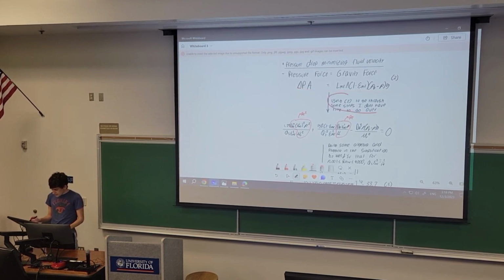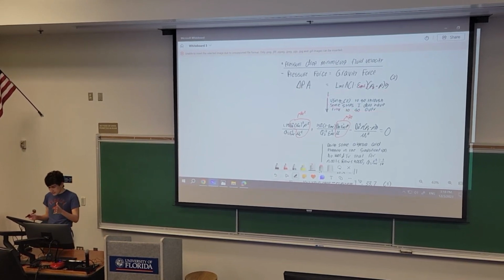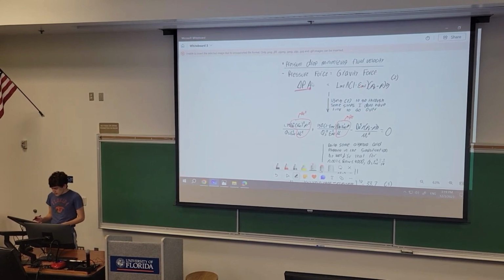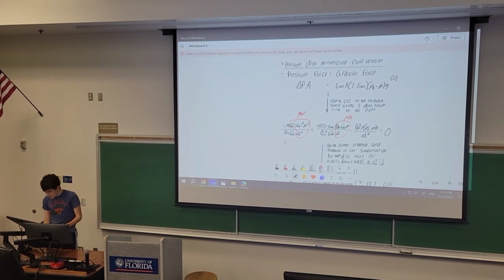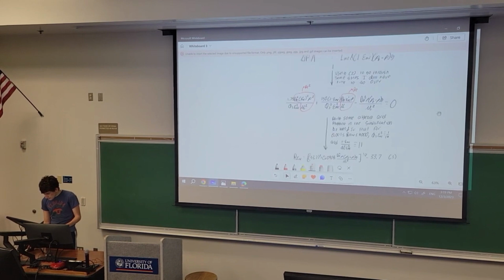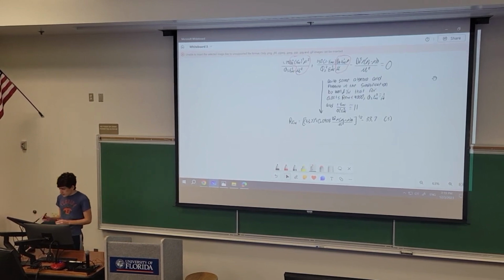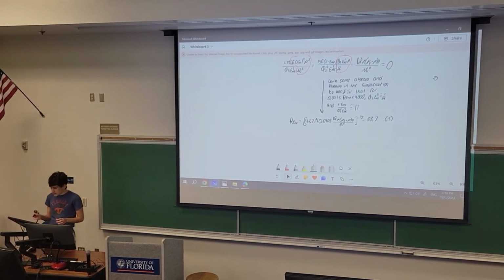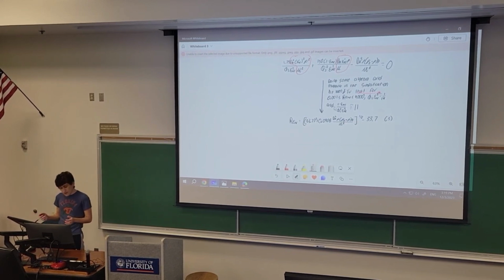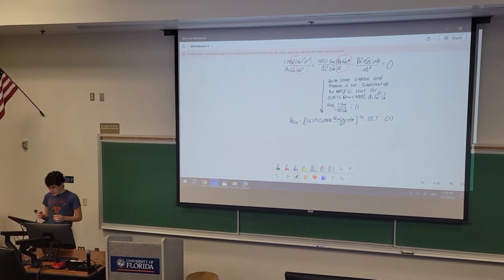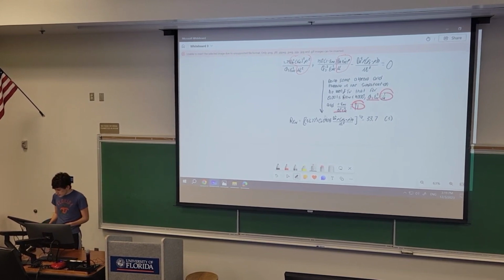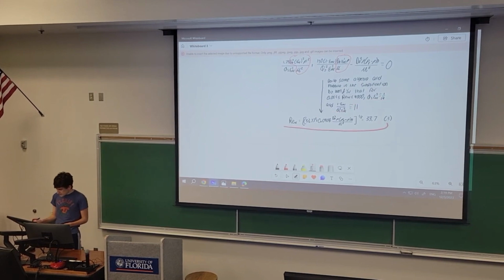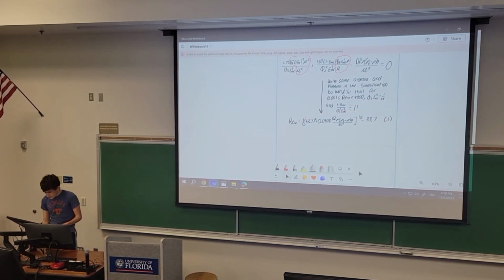And then using this equation, and also an equation that David derived to get delta P, that I don't really have time to go over, you get this long equation where Reynolds number shows up twice, which is why Reynolds number is pretty important to this problem. And then furthermore, doing some algebra and plugging in the simplification made by researchers Wen and Yu, that for a Reynolds number greater than 0.001 and less than 4,000, this term equals 1 over 14, and this term equals 11. Then you get this more simplified equation that is much easier to use.